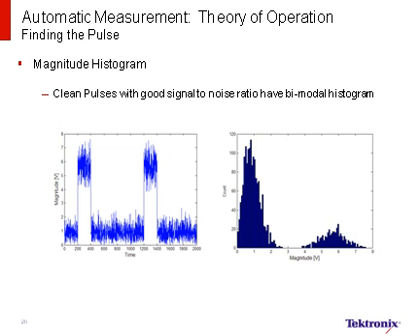The simplest way to detect the existence of a pulse is to generate the histogram of the magnitude versus an acquisition record. If the pulses are relatively clean and have a good signal-to-noise ratio, there should be a bimodal distribution on the histogram. A large grouping will appear in the center on the noise level if present during the off time, and if the duty cycle is less than 50%, a lesser grouping will appear at the top level of the pulse. If the magnitude histogram method works in most cases, a pulse can be detected, and this is the fastest form of automatic pulse detection.